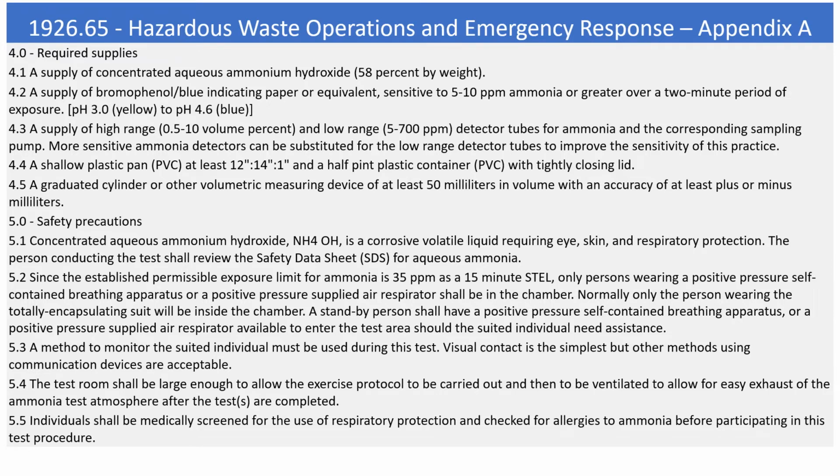Since the established permissible exposure limit for ammonia is 35 ppm as a 15-minute STEL, only persons wearing a positive pressure self-contained breathing apparatus or a positive pressure supplied air respirator shall be in the chamber. Normally only the person wearing the totally encapsulating suit will be inside the chamber. A standby person shall have a positive pressure self-contained breathing apparatus or a positive pressure supplied air respirator available to enter the test area should the suited individual need assistance.